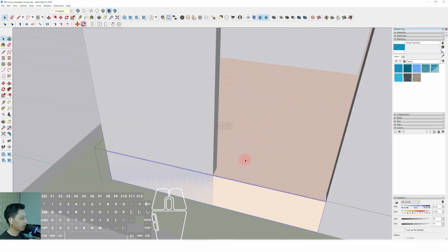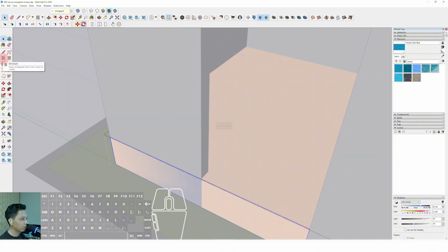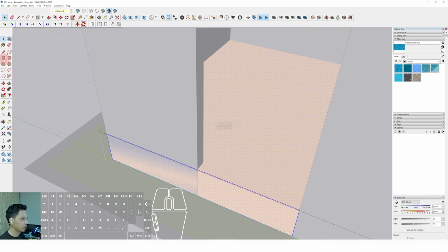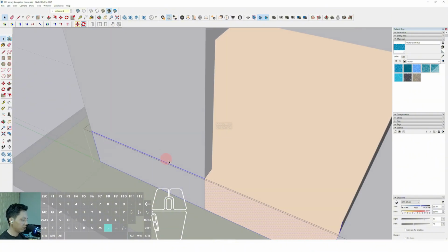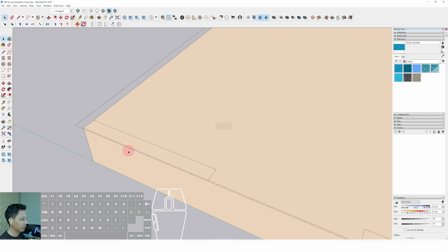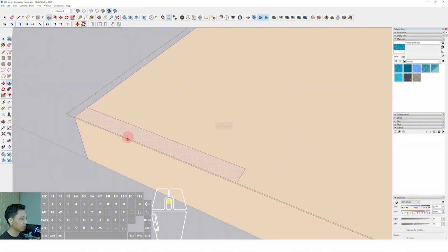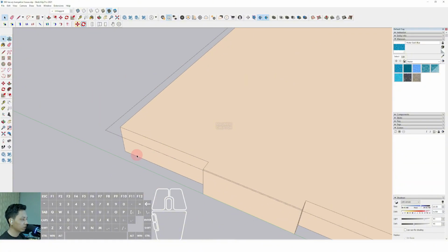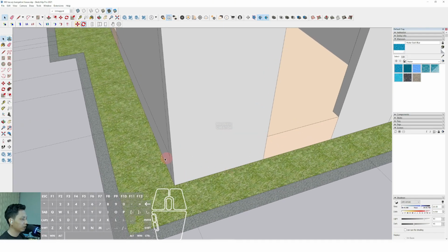Okay, just like this. We can just triple click this floor and select the rectangle or rotate rectangle. It depends on your comfort when you adjust it, but I personally select the rectangle for easy marking in here. Okay, and after we get the surface in here, we can select push, click the surface and push it to the bottom until the limit, so it can be clear space in here.